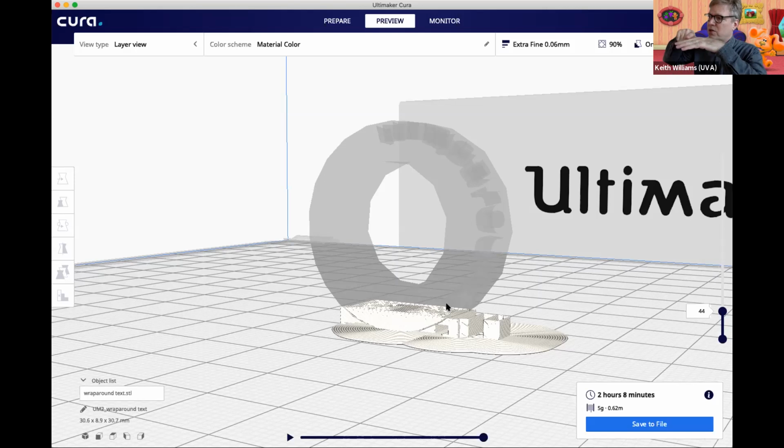And that different material can then be dissolved after the print is finished. That's how I got that really super duper high resolution print on that gyroid cube. We printed it with dissolvable support. So you take the model after it's printed, the whole thing, and you toss it in some NaOH water, just lye, right? And that dissolves away the dissolvable support. And then you're left with just the plastic, and it's really beautiful.